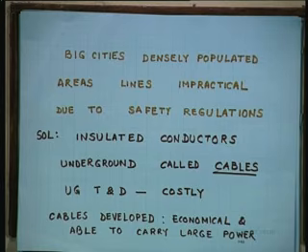New York, I told you, is one city or metro where there is no space even to stand. So, where is the question of having more and more transmission lines? The biggest cable network in the world is in New York, and there you need reactors for controlling, because the capacitance is too much.